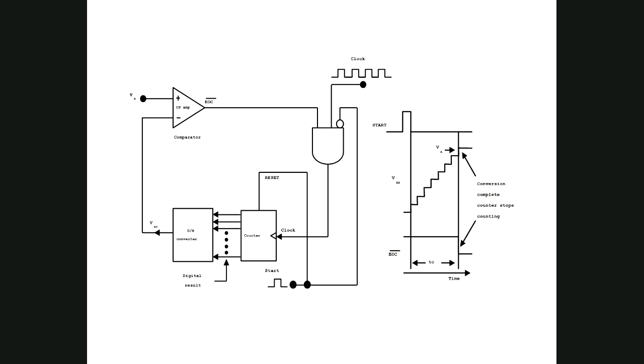So we have checked this start pulse here. Start pulse has two things. It goes up and then it goes down. When the start pulse goes from 0 to 1, what happens? This one will go to reset, so the counter will be reset. Counter reset means initially all will be 0 0 0 0, right?